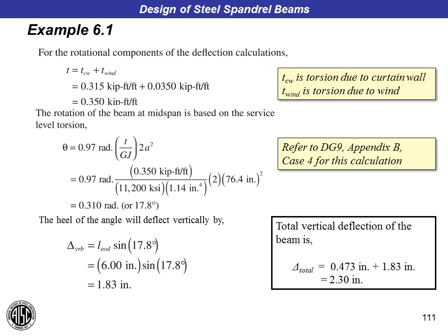So providing a roll beam laterally restrains the bottom flange of the beam, not only for torsion, but also for lateral torsional buckling. For most floor framing, I will typically provide a roll beam perpendicular to the spandrel beam, in part to deal with the lateral forces on the spandrel beam from the facade connection. So not just the torsion, but also the out-of-plane load. And I generally try not to span the full 30 feet because I find the member size just becomes excessive when I try to do that.